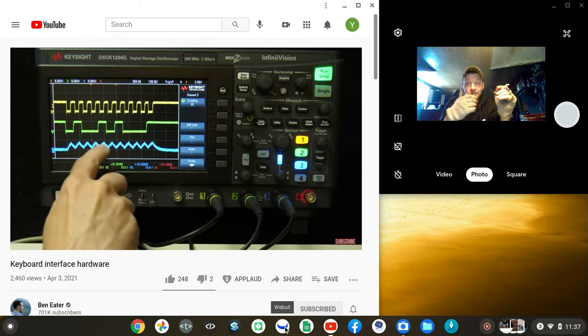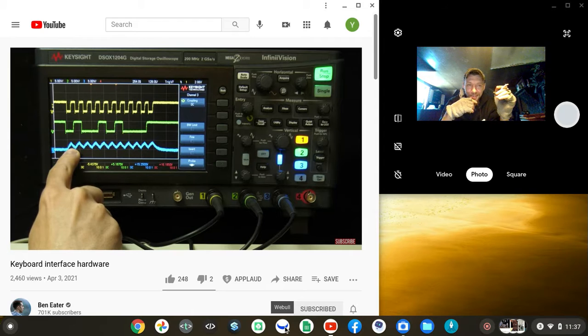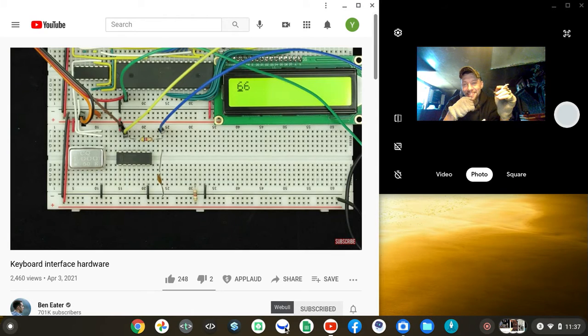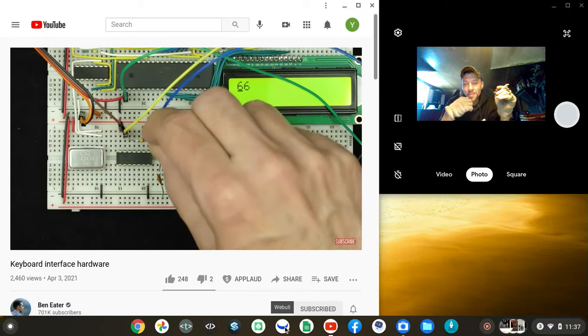And we can change the shape of this by adjusting the size of the resistor and capacitor that we're using, to change the rate that it's charging and discharging. So this resistor I'm using here is just a 4.7K resistor, which I just kind of grabbed randomly.